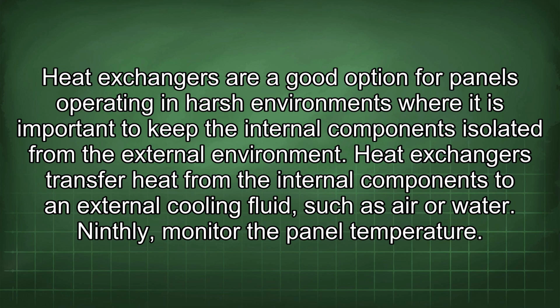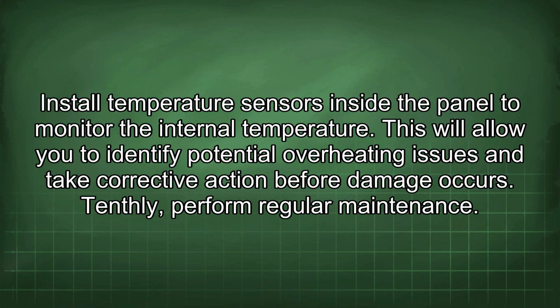Ninthly, monitor the panel temperature. Install temperature sensors inside the panel to monitor the internal temperature. This will allow you to identify potential overheating issues and take corrective action before damage occurs. Tenthly, perform regular maintenance.